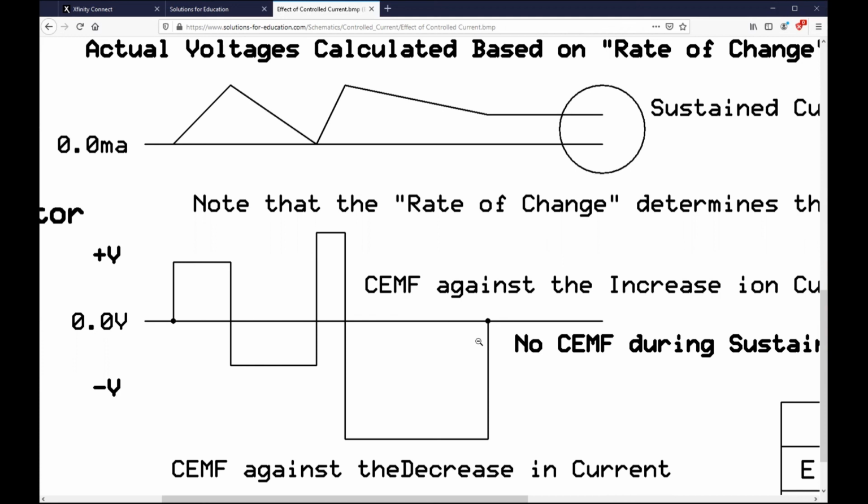By the way, the 5-inch guns on a ship are controlled by an amplidyne, which is a motor generator combination. And what you've got, because I was the guy that tuned those amplifiers, is feedback that comes in and directional control. And what happens is this amplifier feeds the field with the proper amount of, shall we say, excitement. And as a result, the excitement in the armature is carried to the motors on the gun mount.